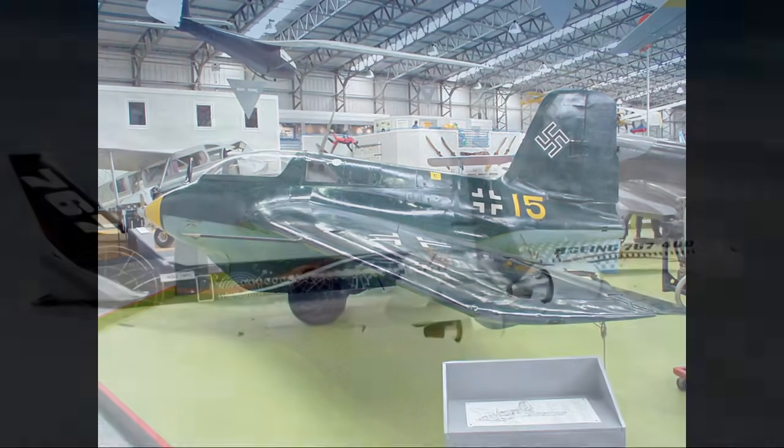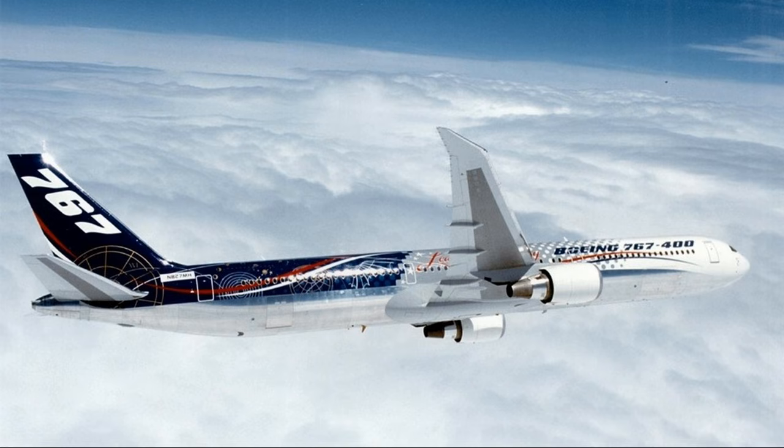In a typical jet engine, as the aircraft climbs, power available decreases because there's less air to use for combustion. Note, many modern airliners get around this issue via flat rating, meaning if they need 65,000 pounds of thrust, the designers put on an engine capable of generating, say, 80,000 and "flat rate it," meaning they just limit it to 65,000 pounds at lower altitude. That way you can maintain that level of power up to some higher altitude. However, in terms of actual maximum possible thrust from a given jet engine, power decreases with altitude and with temperature.